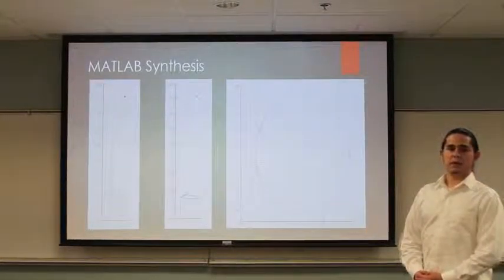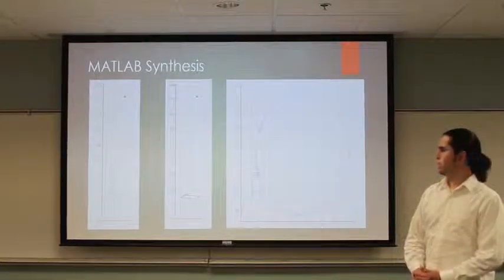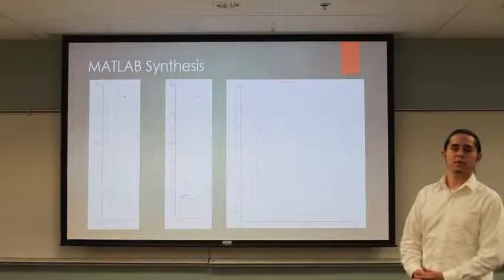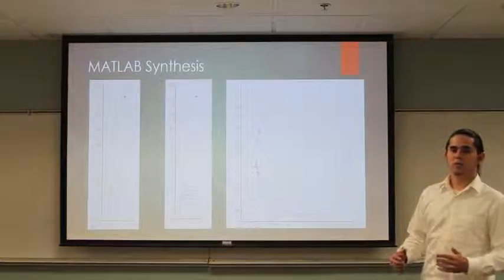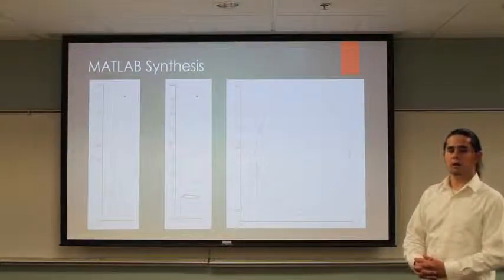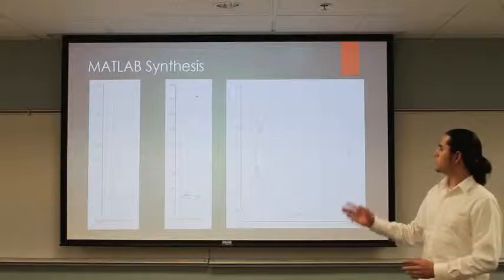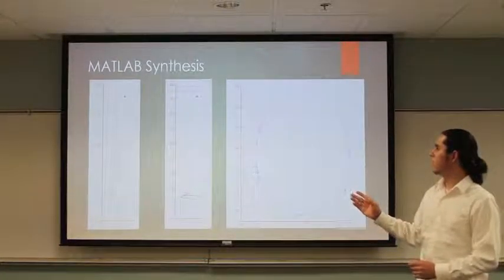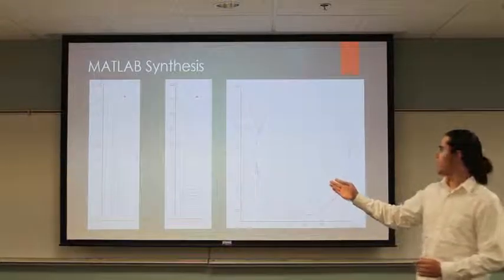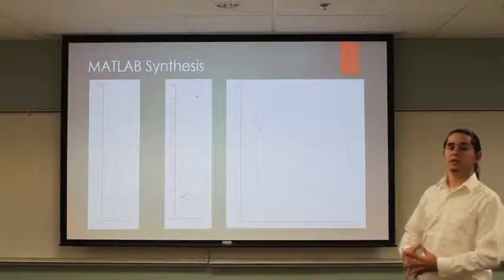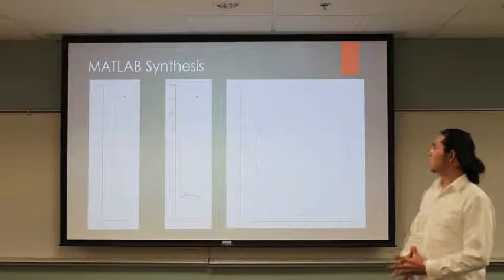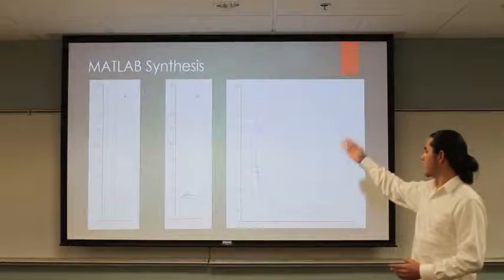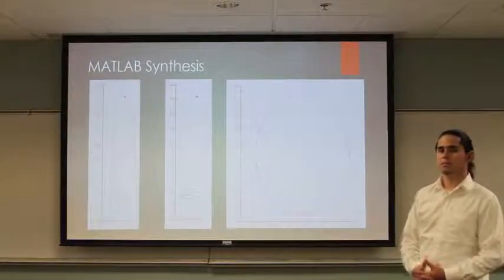The synthesis of the slider crank was conducted in MATLAB. What's depicted in the pictures here is a graphical representation of the numerical method used to find the resulting geometry. First, poles P12, P23, and P13 are located, shown by the blue, green, and red asterisk in the first picture. A line was drawn between pole 13 and pole 12, shown by the cyan line in the second picture.